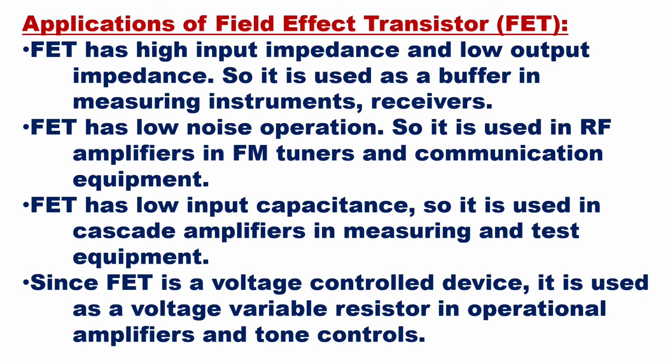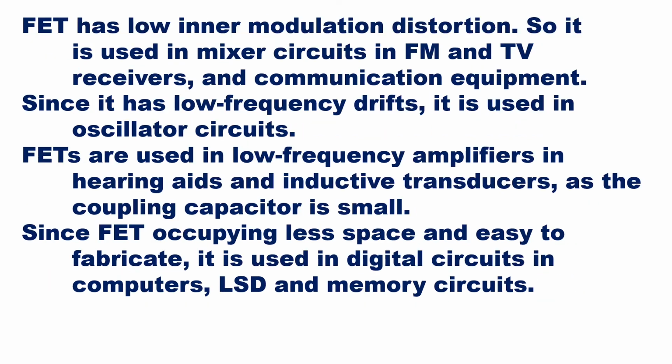Since FET is a voltage control device, it is used as a voltage variable resistor in operational amplifiers and tone controls. FET has low intermodulation distortion, so it is used in mixer circuits, in frequency modulation FM and TV receivers and communication equipment. Since it has low frequency drifts, it is used in oscillator circuits. FETs are used in low frequency amplifiers, in hearing aids and inductive transducers as the coupling capacitor is small. Since FET occupies less space and is easy to fabricate, it is used in digital circuits, in computers, LSI and memory circuits.